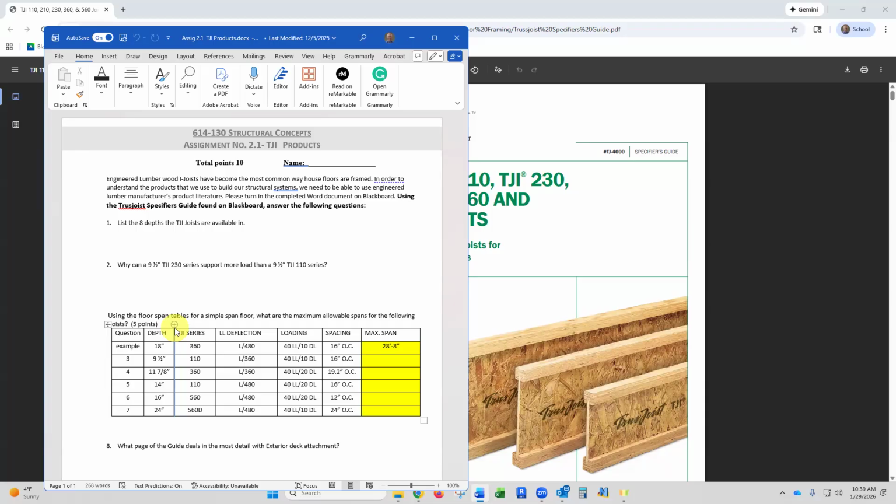It's going to affect ceiling heights, not really, but as much as your stairs. Okay, so if I'm in my basement and I've got a 9.5-inch deep floor above, I've got the same ceiling in my basement, but my stair has to go up that extra 9.5 inches to get to my first floor. Now imagine it's 24 inches deep. I've got to add more treads and risers to my stair to get up there.